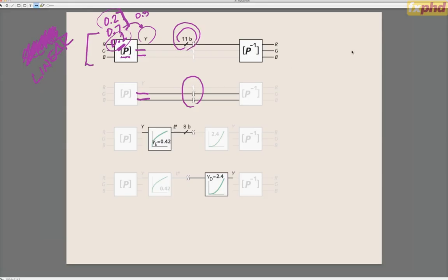We'd really like to be able to shrink that data path down to about 8 bits for commodity consumer class video. In order to do that, you've learned about the CIE L-star function, which is about a 0.4 power function. And that's highly economical because 8-bit components are really convenient.